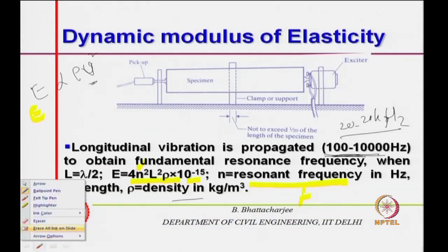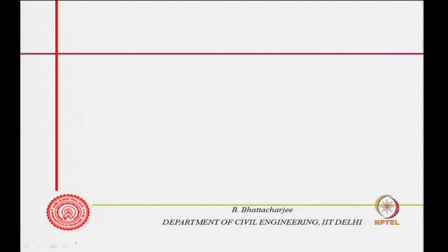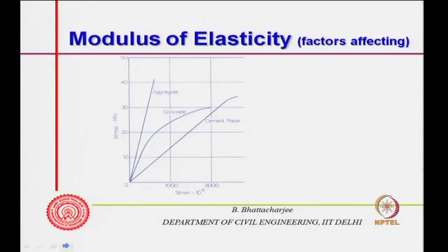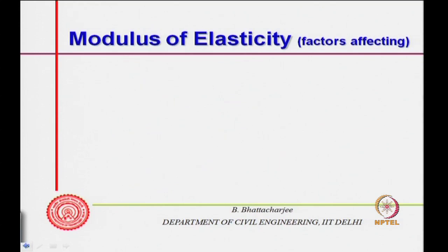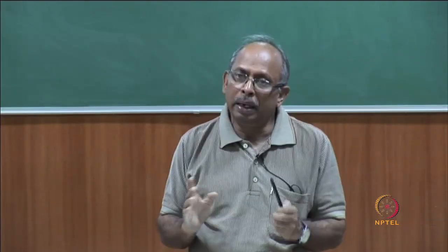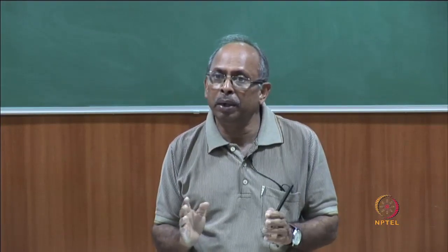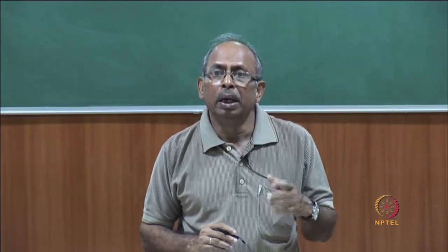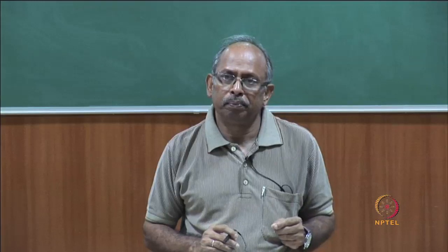elasticity. So, this is how we find the dynamic modulus of elasticity, and we said that the dynamic modulus of elasticity is the initial tangent modulus, because no cracks have occurred in an uncracked specimen. We are trying to find the modulus of elasticity. Usually these values are higher.